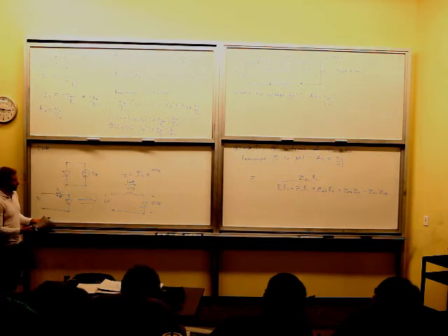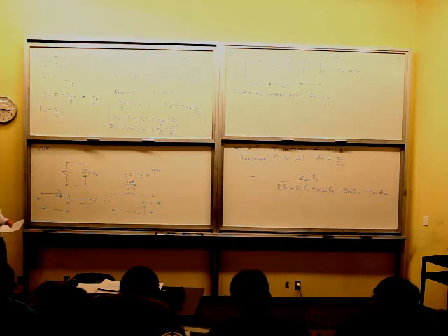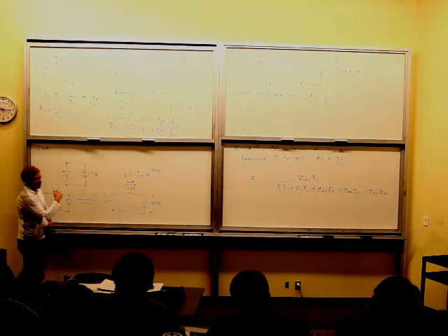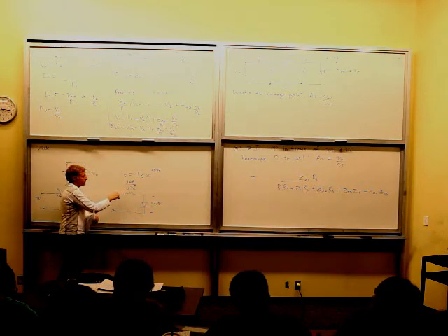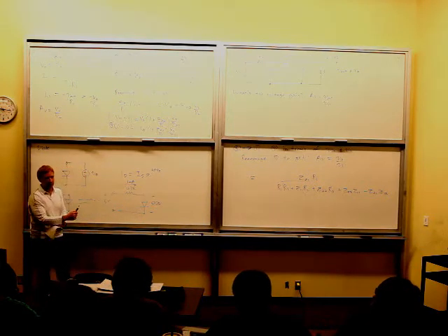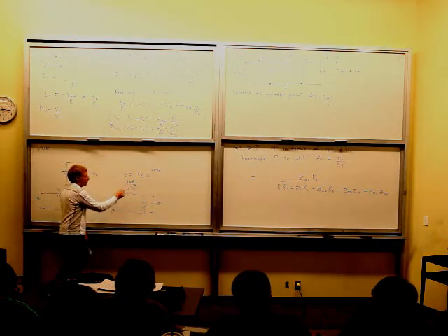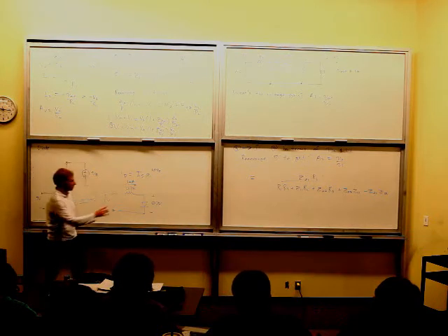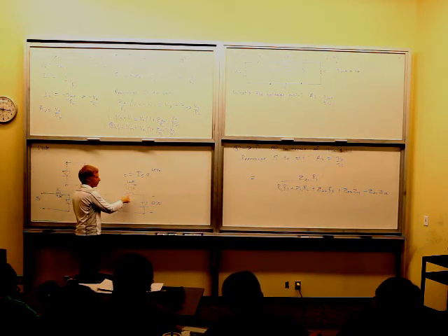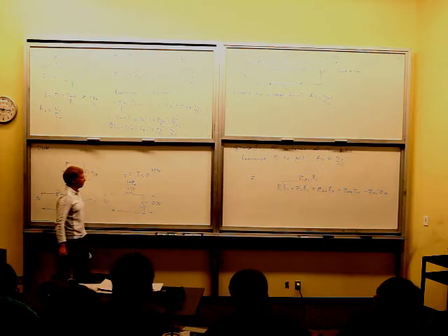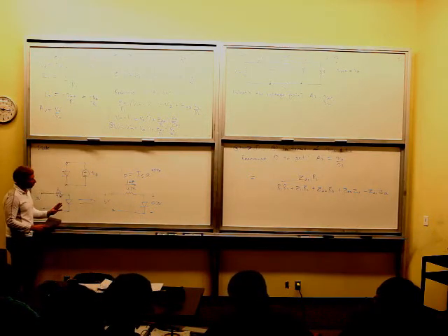So in the cases that we're looking at here, where we're talking about biasing a diode or biasing a BJT, it's the resistors outside of the nonlinear component that make our life easier, because now we're putting the burden on the resistors instead of the burden on this exponential equation. We're now switching over to a linear Ohm's law to determine the current through that diode as opposed to that diode equation.